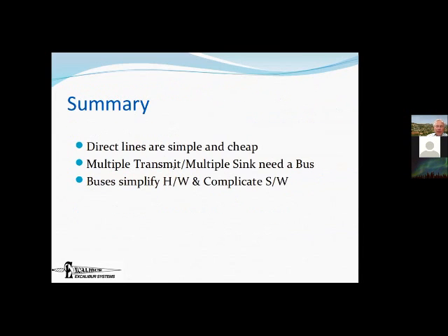Okay, and that's used on both new Boeings and new Airbus planes. So in short, there are many ways to skin the particular cat that is a digital bus. ARINC-429 is one of the simplest methods of doing it. Simple means inexpensive usually.